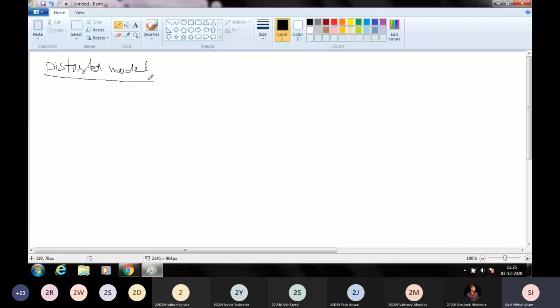Particularly in case of shallow rivers where depth is small compared to width, without distortion the depth of flow in a model will be so small that measurement may not be accurate, and surface tension effect will be predominant, which will not be present in a prototype. Hence it is necessary to distort the model in a vertical direction.